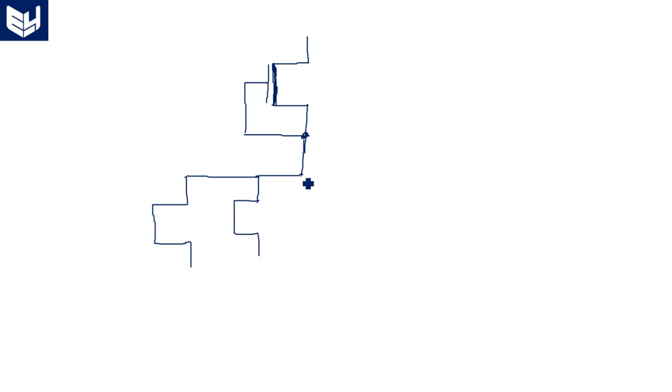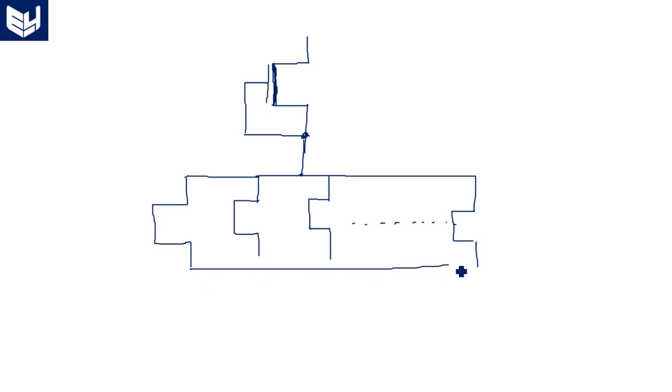So a depletion mode transistor, as I said, a depletion mode transistor here, this is connected here back, and now multiple inputs we have. Multiple inputs means more than one input. So here we have one transistor, here we have one transistor, here we have a set of transistors, group of transistors connected in parallel for which realization? NOR realization. Don't forget that for NOR realization only we connect them in parallel.